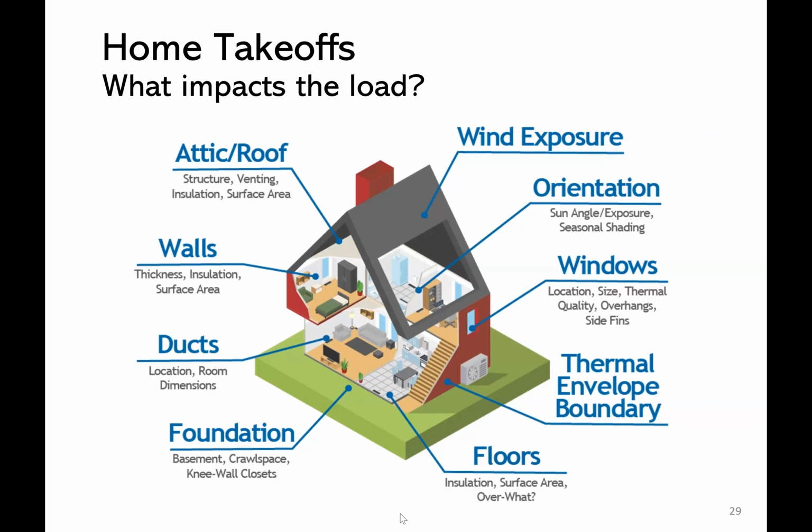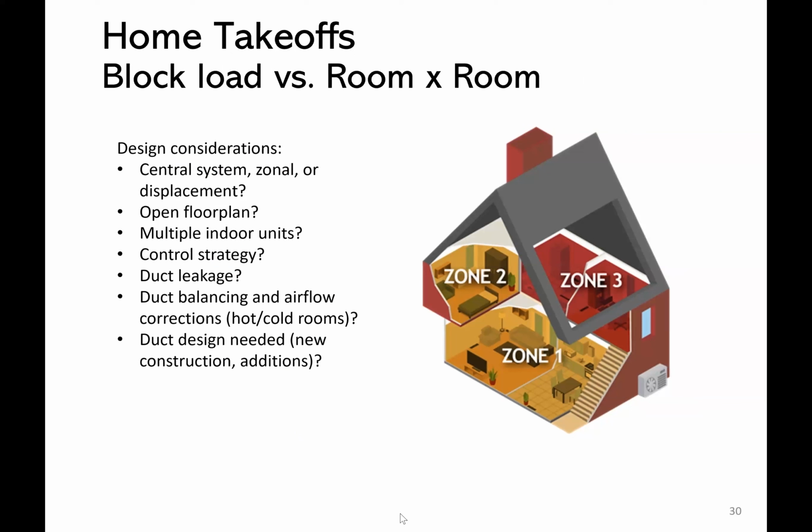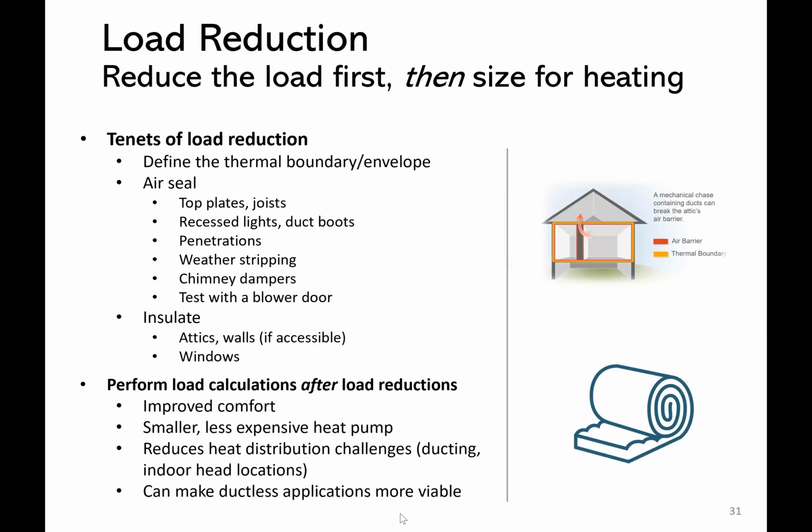Load calculations can be performed for the entire home, often called block load, or room by room, or by specific areas. These design considerations should be reviewed when determining how best to model the building. In all cases, it is significantly better to reduce the load first, then size the system.